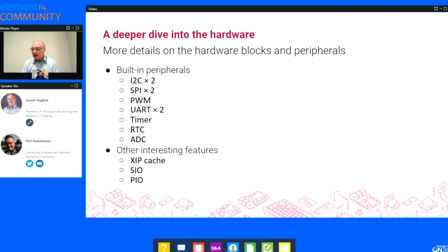On the RTC, we mentioned that just now with the question on the accuracy. As I said, I don't know the answer to that offhand, but it's worth noting that the Pico and the RP2040 themselves don't have any sort of battery backup. So if you are going to use an RTC and want to retain the clock over a power down, you have to incorporate some sort of battery system on your device. So it's worth remembering that.